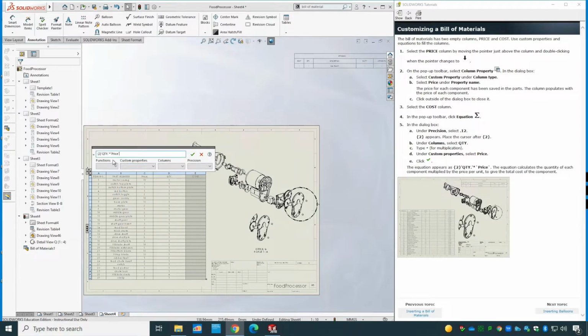So that's the formula. I click OK, and you can see the cost would appear here. For instance, we have 2 switches, and the price becomes $2 or £2, whatever the unit of this one actually is. So this is the bill of material, which is really important to have as one of the documents whenever you have the exploded view.